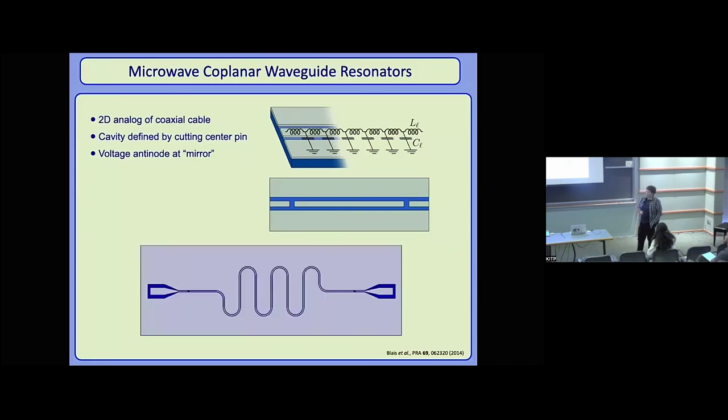In practice, they look more like this because we need to deal with our roughly 8 millimeter wavelength, and so for compactness, we tend to fabricate them with meanders like this. The fact that we can do that is really key to the devices and some of the places that we want to go. If you don't like thinking about hardware, it's a harmonic oscillator, with charge and flux instead of position and momentum, but basically this is our favorite harmonic oscillator.